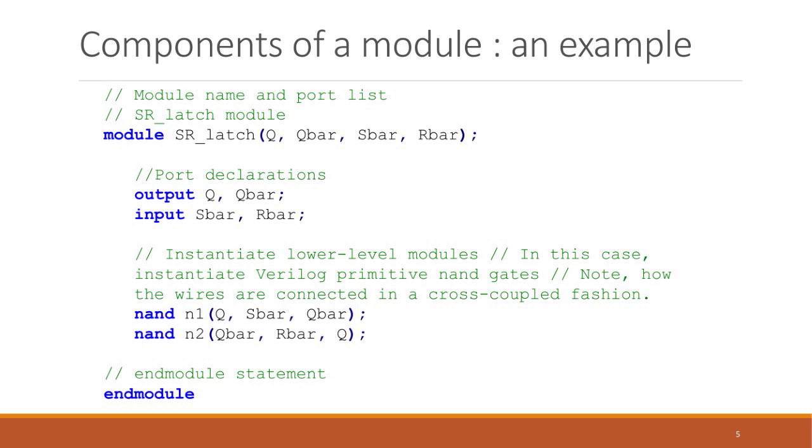They are not multiple bit wires. If they were multiple bit wires, or buses as we call them as well, we would need to specify the size of the bus or the multiple bit wire as well. We actually saw an example with multi-bit ports in our previous lesson's example, where we tried to model an adder, and we'll look at some such examples later in this lesson as well.